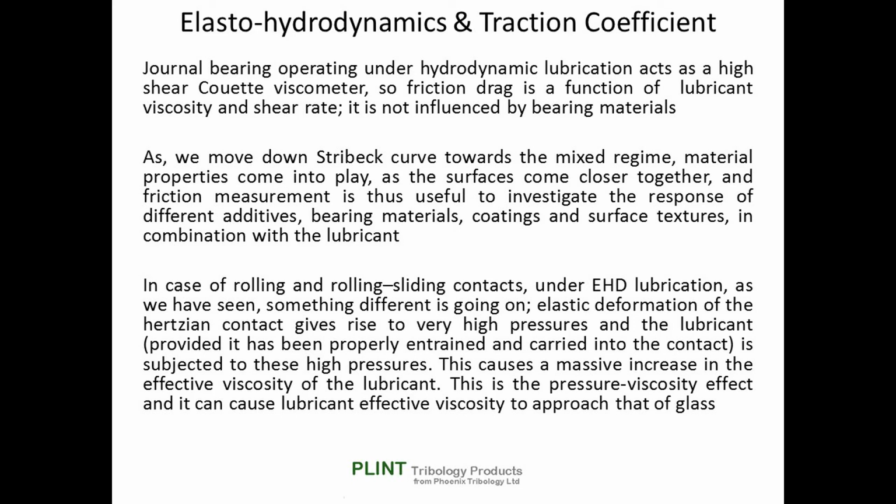As we move down the Stribeck curve towards the mixed regime, material properties come into play as the surfaces come closer together, and friction measurement is thus useful to investigate the response of different additives, bearing materials, coatings and surface textures in combination with the lubricant.